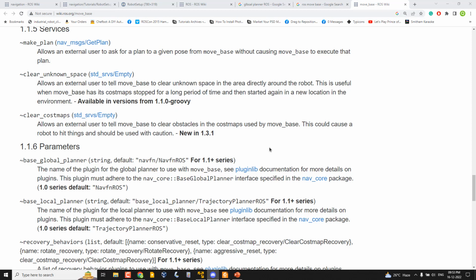So sometimes we may need to fine-tune the controllers. For example, for turning or rotating the robot, we may need to fine-tune the differential drive controller, if you are working with a differential drive robot. Mostly, if you are doing some prototyping application, you can simply take the differential drive controller and whatever planners you like.